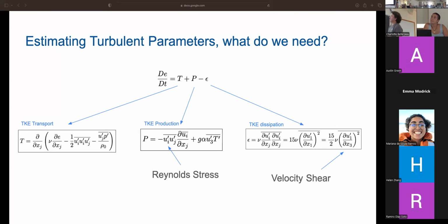Looking at this, there's a bunch of overlapping values that we want to see. Specifically in the TKE, you'll see a u-prime bar, which is what we call the Reynolds stress, which you guys have heard a lot about. Any of these dU/dz terms, we call them stresses. These are the kind of things that you want to keep an eye out for, and hopefully we'll talk about how you get those.